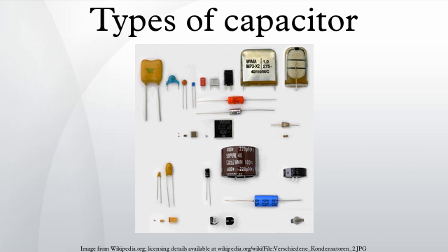Some ceramic capacitors of special shapes and styles are used as capacitors for special applications, including RFI/EMI suppression capacitors for connection to supply mains, also known as safety capacitors, X2Y registered trademark capacitors for bypassing and decoupling applications, feed-through capacitors for noise suppression by low-pass filters, and ceramic power capacitors for transmitters and HF applications. Diverse styles of ceramic capacitors.